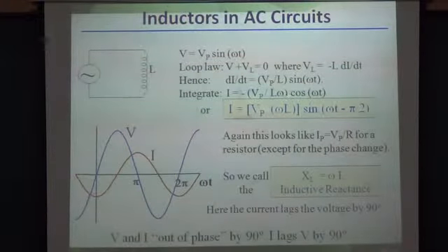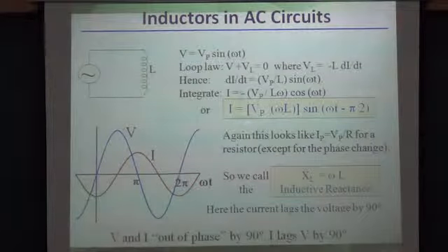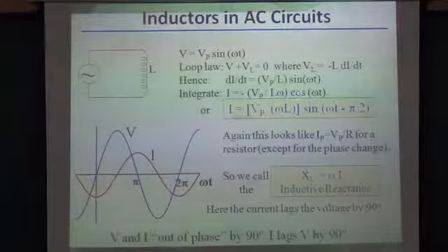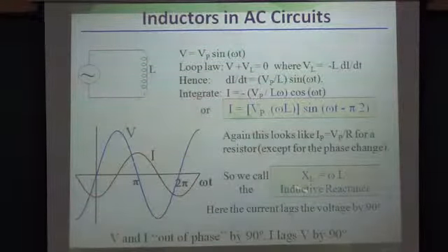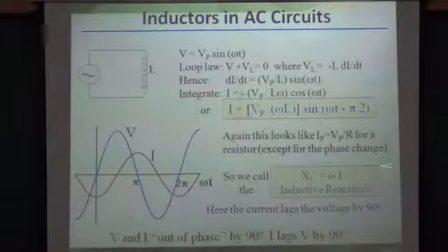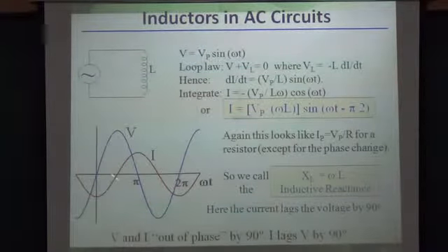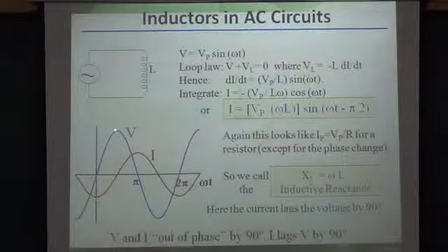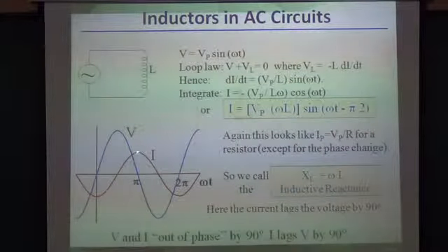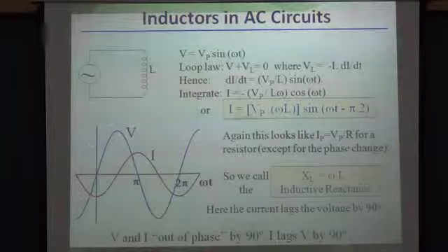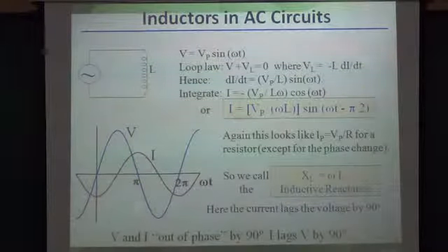So here I is there, so I must be V by R. So therefore this omega L must be nothing but the inductive reactance. And in this case you can see my voltage is first going to peak, before the current, and hence the voltage here is leading.